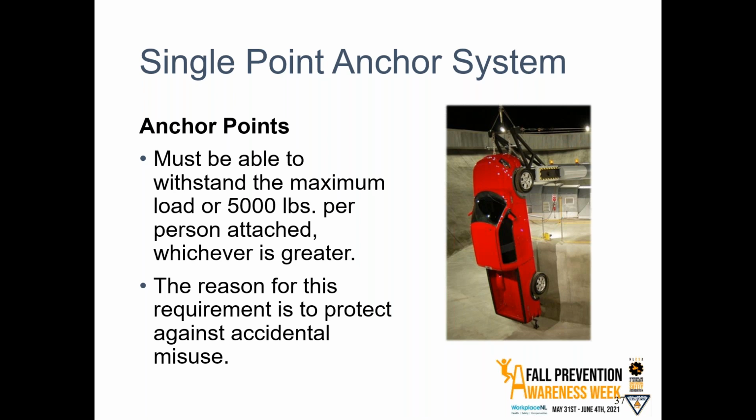I did actually recently see a picture of someone who had been tied off to some duct work here in the city area. So people are still tying off to things that they shouldn't be. Certainly a good rule of thumb is if you wouldn't hang a full-size truck off of that item, whatever it is that you're using to attach your system to, is probably not the place where you should be tying off. Keeping in mind too that it's not just your weight that the system's going to have to support, but the force of your weight falling and then coming to a sudden stop, which generally speaking is significantly more force than your weight alone.